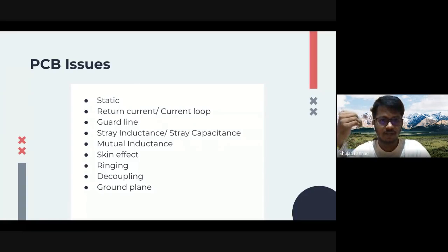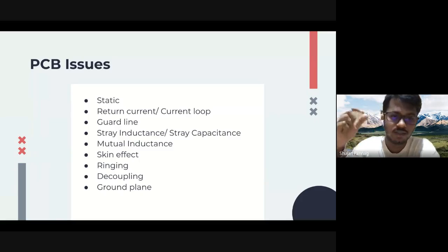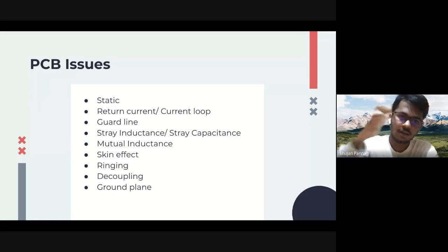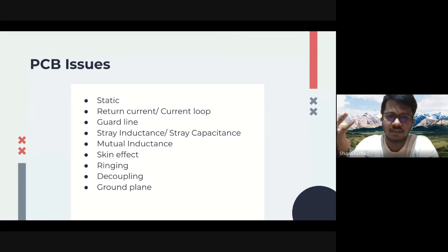So it takes off some higher frequency components, because usually if you simulate a PCB in software, the frequency components of the noise will be around 50 megahertz or less. So you figure out the average noise frequency, find the appropriate capacitor value, and put it in parallel, and it decouples or bypasses the AC components. For the DC component, it acts like it doesn't even exist, because the impedance becomes infinity, right? So the DC component is allowed to flow, and the AC component it sinks to the ground.